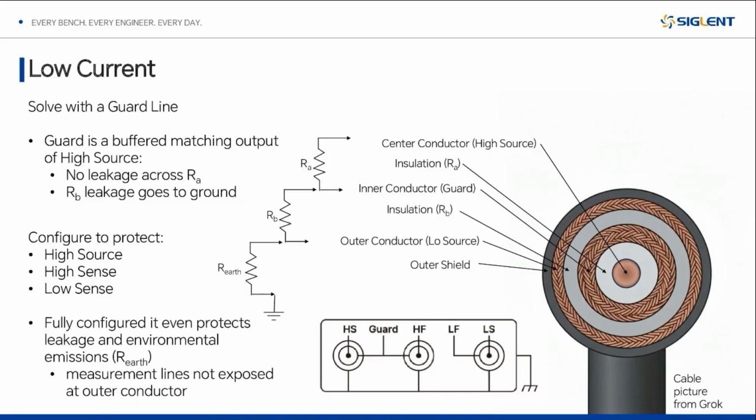So you can use these triax configurations with 3 conductors to really eliminate that current leakage, and you can earth shield these as well to eliminate a lot of those environmental impacts, right?